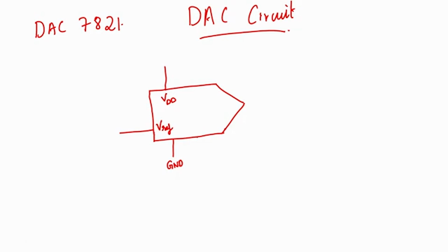These ICs, except for oscillators which are self generating, with only power supply they can generate oscillating outputs. Most of the other ICs would need an input. Here because it is a DAC we need the input. What is the input? Our input is a 12-bit parallel digital input, because it is a digital to analog converter. So that is D11 down to D0.